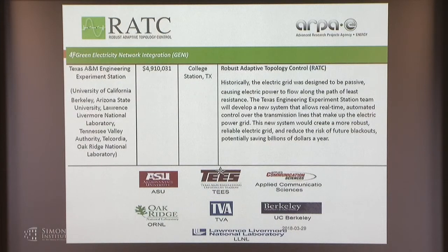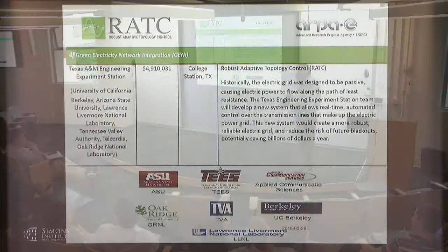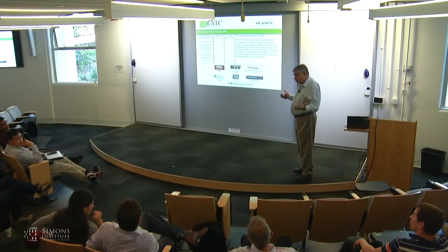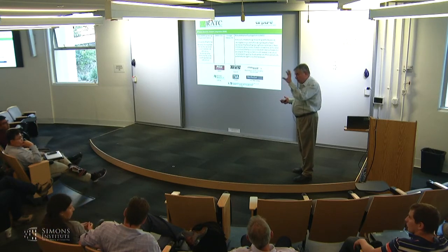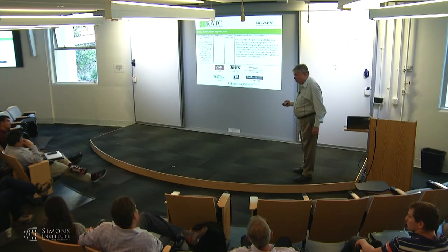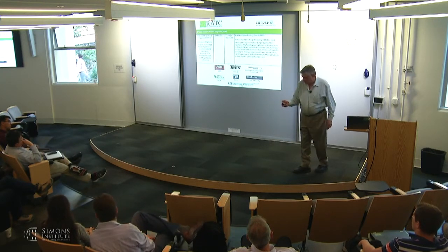Is there any issue of instability due to transients? Well, we can check stability, and we always do that. But stability usually is checked offline. What I meant was instability due to transients, when you change topology, during the transient. That's a problem that we have considered. That's possible. But when we do that, first we propose lines to take out, then we do simulations like you always do when you take actions, to see what it will do to the system, and you do all these online simulations. And that's something that we have considered.